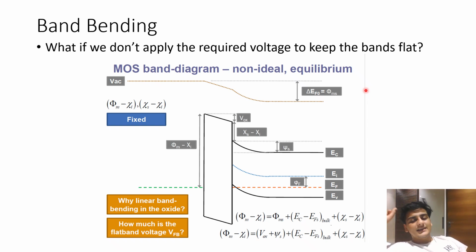Now this bridging is essentially done mainly in two regions. Part of it is done in the oxide, and part of this bridging or band bending happens in the semiconductor. And when you get far enough away from the edge, this band becomes flat. And obviously, this conduction band and valence band follow the vacuum level because they're defined with that as the reference.